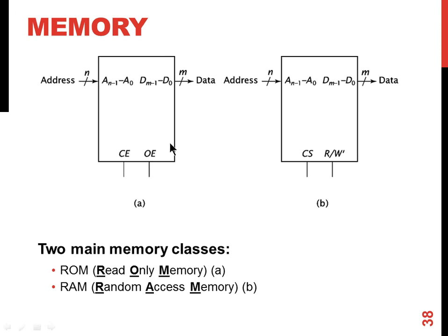Typically, these are the ports, or the pins, required to make the memory work. There is a chip enable to make the memory operation enabled. Output enable is used in case of read operations, read from the memory. There is a data port. Depending on the width of the memory, the data port will match that value. Then you need an address port.